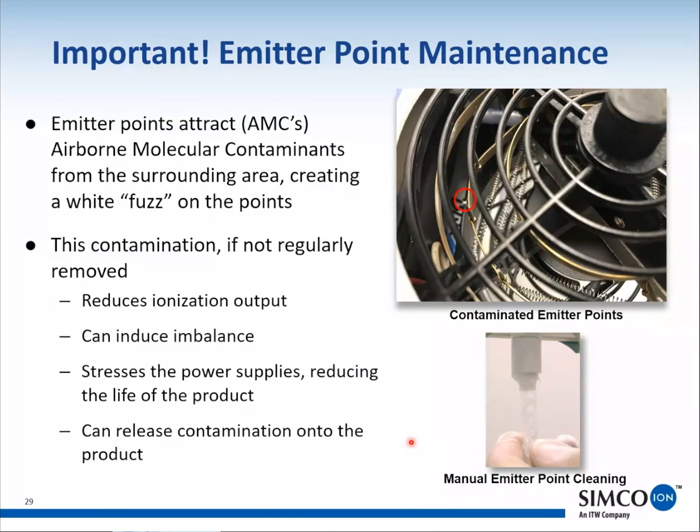Next question, actually coming from Clonmel, Ireland. The question is, at what range are these ionizers effective? It all depends on how much airflow you can tolerate. The overhead blowers, let's call those the most common ones, are generally effective within 3 to 4 feet, depending on which ionizer. Some of our products have what we call a whisper mode. I mentioned that in the video. You can barely hear the fan running. Those tend to work the best, probably at 1 to 2 feet. You get further than that, and the airflow is just not there anymore.